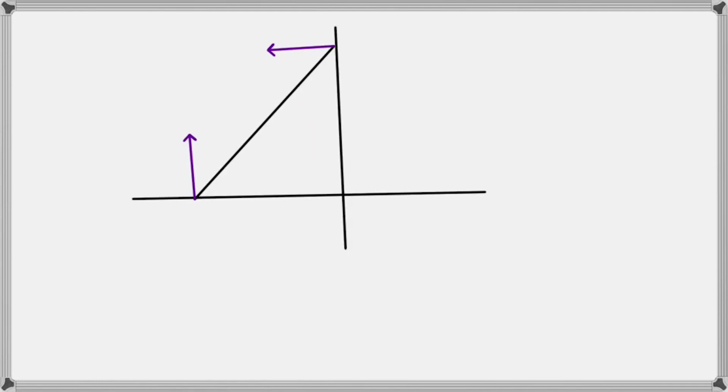Okay. And then what are these? This is the normal reaction at the ground, and this is the normal reaction at the wall. And there's no friction here because it's a smooth wall, but there is friction here. So that's the next force, the friction. Now you see the weight acting, the weight of the ladder. It's N1, that's N2. Let's call this F. And the mass of the ladder is 20 kilogram.